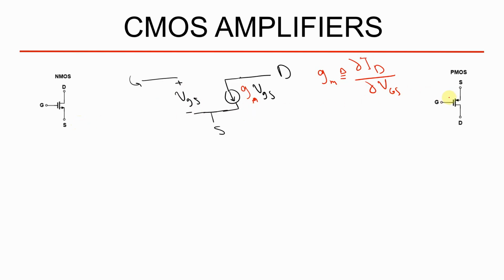And keep that in mind, for PMOS, you can use this as long as you take the plus sign of VGS at the gate and the negative sign of VGS at the source. And by choosing this voltage polarity for VGS, you have to choose the direction of the current gm VGS from drain to the source. So sometimes in some problems I use this approach in the circuit. I mean that this is plus minus VGS and this is the drain current for a small signal model.